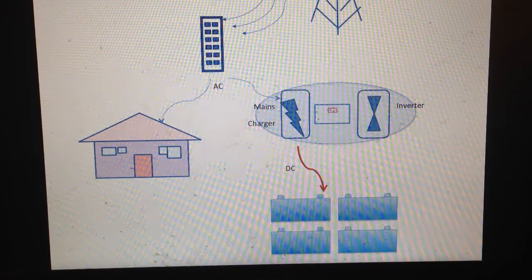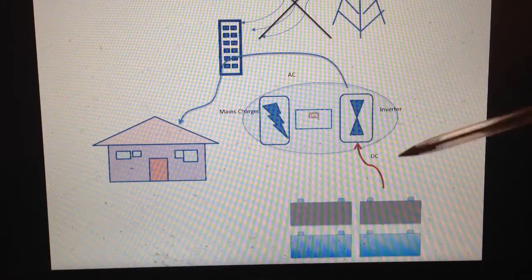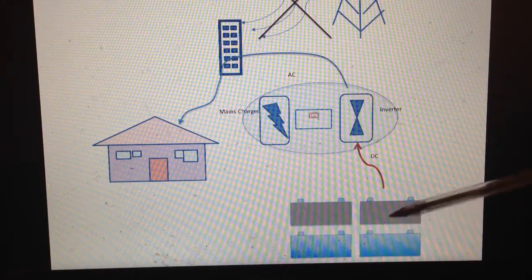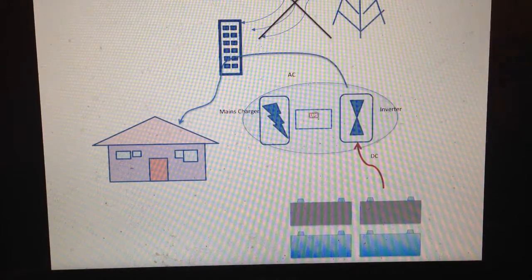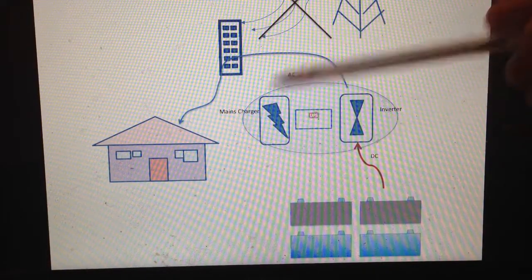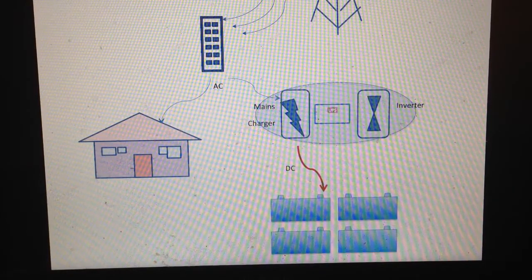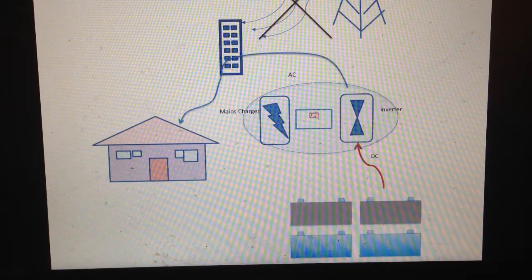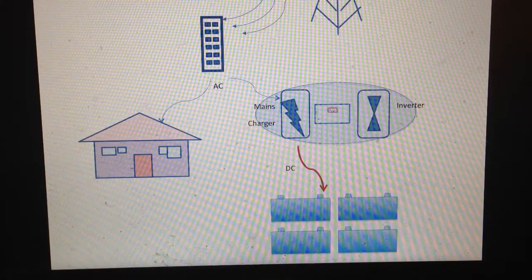And this is good until power goes out again, and power has gone out, and instantaneously the inverter starts pulling the power from the batteries, inverts it from DC to AC and sends it to the house as usable AC energy. So this is something that can keep happening, because then you have power, batteries fully charged, and then you don't have power, you drain your batteries a bit, and then power returns, the battery is fully charged, and you can see this is a good arrangement to have.